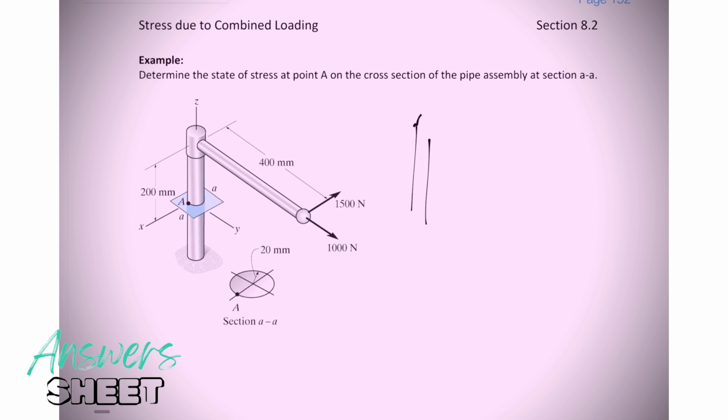I'm going to come over here and redraw this. But here's my cut right there. In 3D, I like to draw my Fx as if it's in the positive x, my Fy, and so on. These are my internal Fx, Fy, Fz at the cut. These internal forces are what we get when we open it up and see those internal forces on that plane. And they really counteract the external forces.